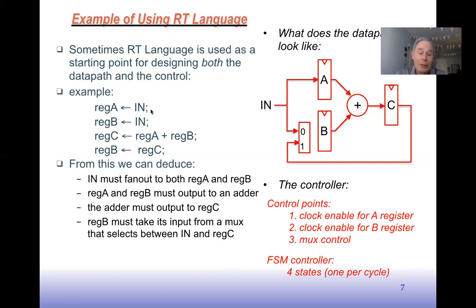If we can come up with a little program like this, we have a technique to turn that into a data path and a control. So we have a technique to make this into a little hardware engine that can execute that. Now, it may not be high performance, as we'll see with my bigger example, and we'll probably get into optimization next time. But once we have this, then we can think about how to optimize its behavior through pipelining and parallelism or something like that.